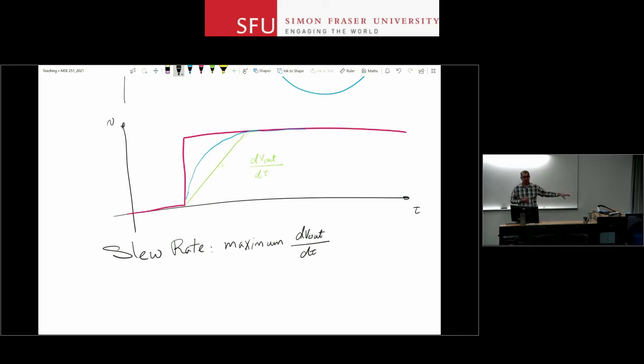So usually this is happening because you have turned off a transistor that was in your signal path. You didn't want that to happen, but the large signal amplitude did that to your op-amp. And you passed the current that was used for biasing of that transistor through a capacitor inside the chip. You get a constant rate of voltage change at the output. You can actually estimate how much the capacitor or the current is if you know one of them. And this is it, right? After that, because your device is off, it doesn't matter what your input does. If you increase the input signal amplitude or decrease it, that will not change.